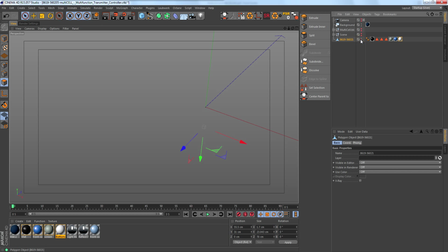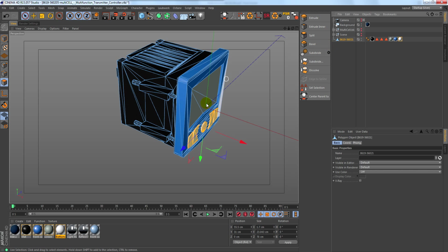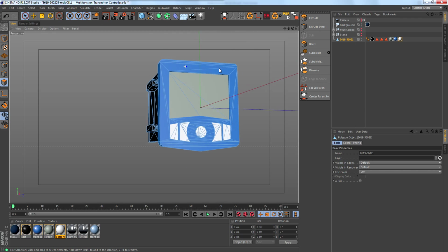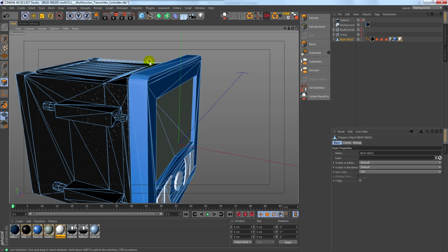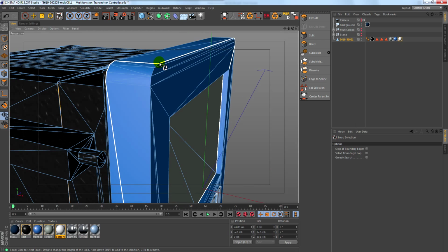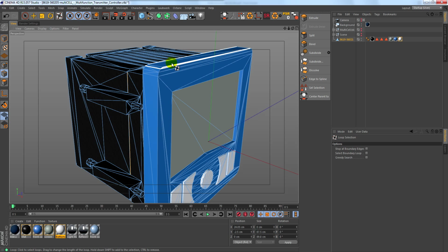Let's get this hidden. Let's bring our CAD file back and deselect these polys, and we're going to start off with this front plate. We need to select this outer spline, so let's come into line mode. Now we can push the keyboard shortcut UL and that will allow us to select the edge. Well, it's not letting us select it. There's so many different lines here connecting to each other that Cinema 4D can't figure out that this line here is our boundary.